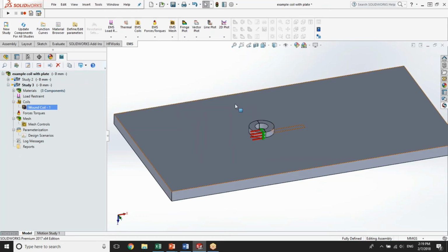If you remember, the depth at which eddy effects penetrate the material is highly dependent on the frequency. Which is very important in this simulation, because we need to keep in mind what is the value of this characteristic depth when defining the mesh size for the simulation.